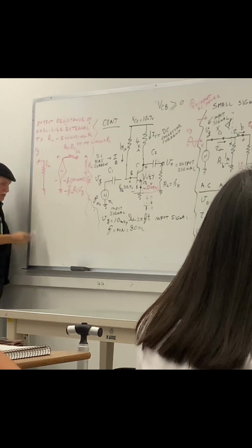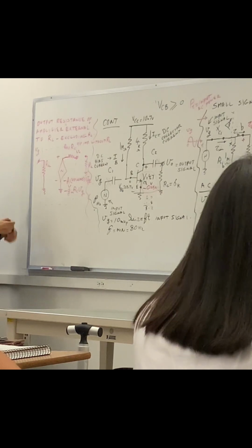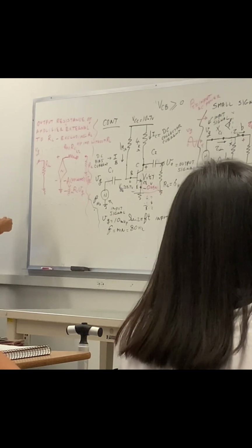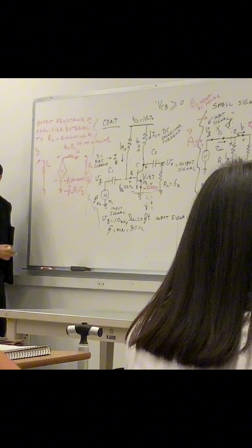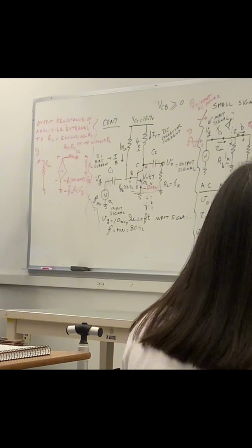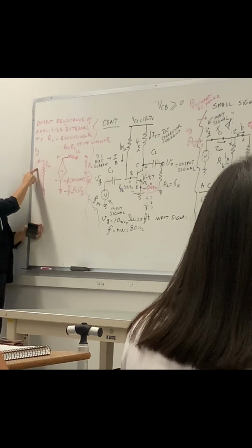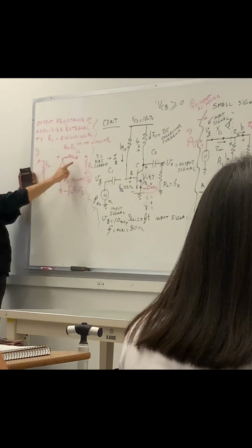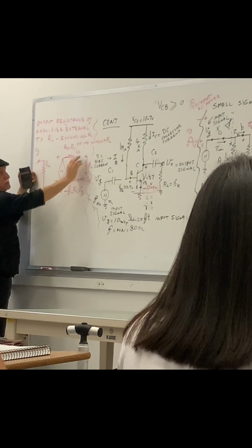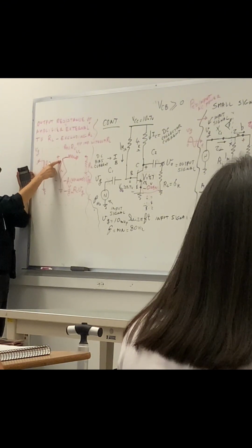Just as a check. What happens if I make a connection here? I bring it back. What will happen to that VO? Again, I just change this question to one step ahead of it. What is the VO in here if you apply a VG over there? Without RL, voltage in there is equal to the Thevenin voltage, always.